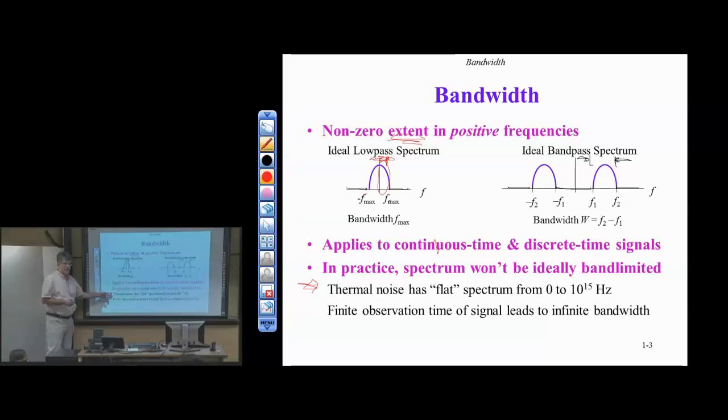Where does it come from for us in electronics? So where does that thermal noise show up? It could be radiation, but in a circuit, what's happening? It could be power dissipation, but what's the physical mechanism? What's moving around? Current. Electrons. So it's a random motion of electrons due to temperature.